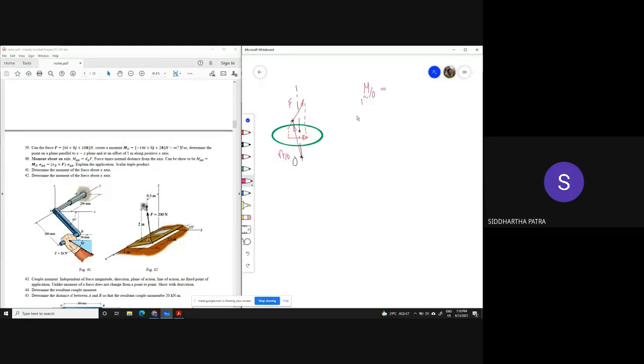Okay, now this moment is a vector and it has its own direction, but we are only interested in the component of the moment that is along this axis. Okay, for example, if I think of this as the plane of the position vector and the force, the moment would essentially be normal to this plane, right? But it's not the total moment that I'm interested in. So this is the moment about O due to that force over there, and the position of P is arbitrary, as we know.